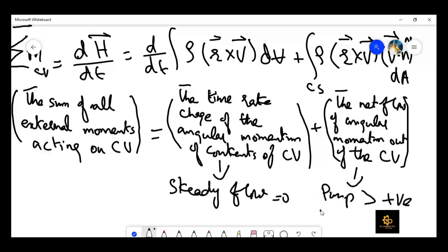Because in case of turbine, we take angular momentum from the fluid by the striking of fluid on the turbine blade, so that the angular momentum of the fluid which is leaving is less than the angular momentum which came in. So basically, the energy has been imparted on the turbine blades. But in case of pump, because we drive the pump by electricity, we are giving that fluid more angular momentum. Right? So this is the basic difference between pump and turbine: in pump we provide work and in turbine we take work from the incoming stream, right? So I hope that this point is clear.